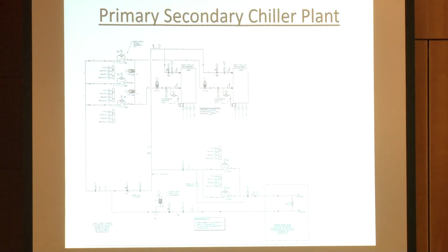Then you're going to start in the chilled water plant. Most of the time in bigger projects, we're always going to deal with primary, secondary chilled water plants. It is becoming much more popular now to do a primary plant and not have the secondary, but I don't know, probably only like 10 or 15% of the projects are going only primary.